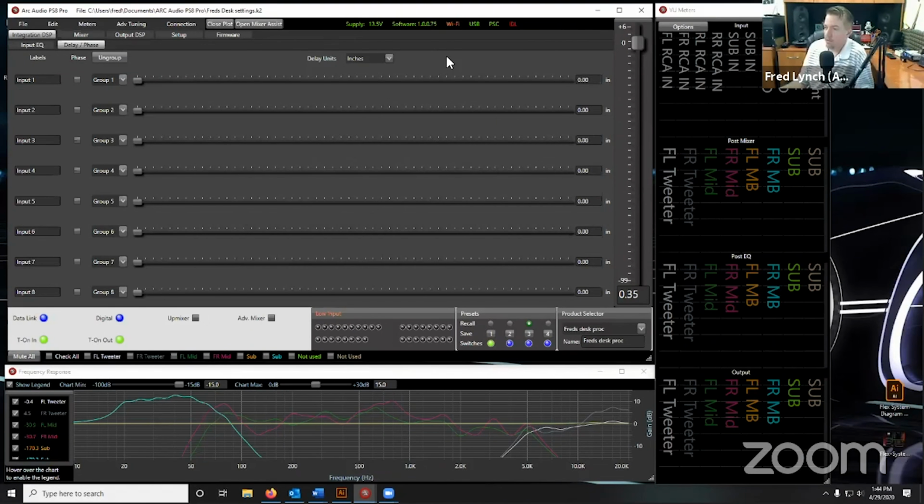To be honest with you, that is going to depend on the hub. We have had some people who had 4 USB ports hooked up to 4 processors, not a problem. We've had one person who did 1 USB connection back to the hub and bought a very crappy hub. I think he went through 7 or 8 different hubs before he found one that would work, because not all hubs are built the same. The thing to remember is when it comes to USB, every connector in a USB signal degrades the signal. And if you check with USB, they actually only guarantee communications up to about 6 feet.